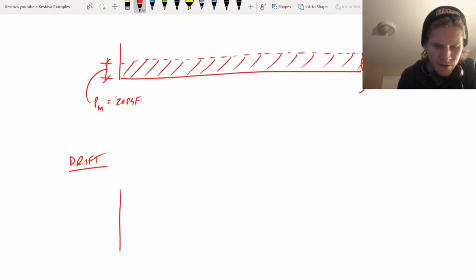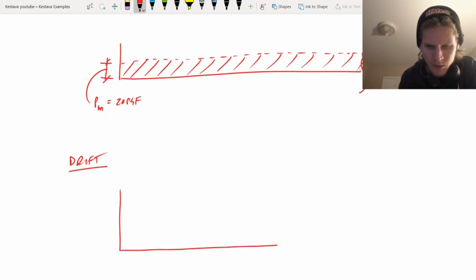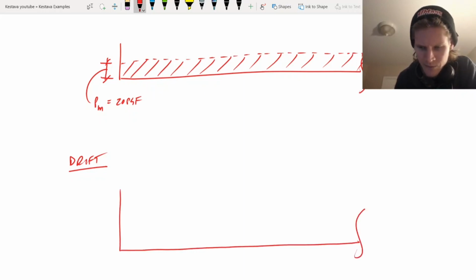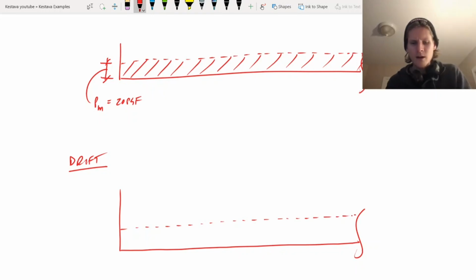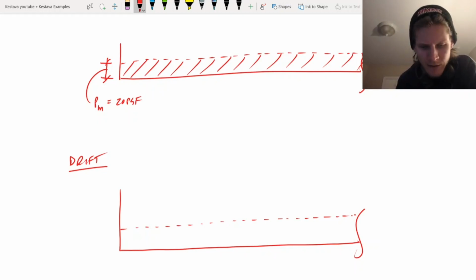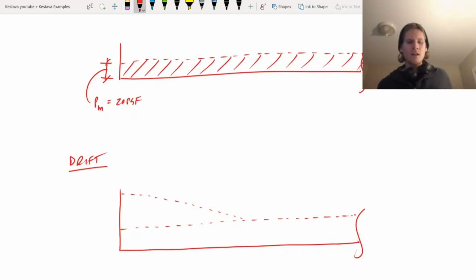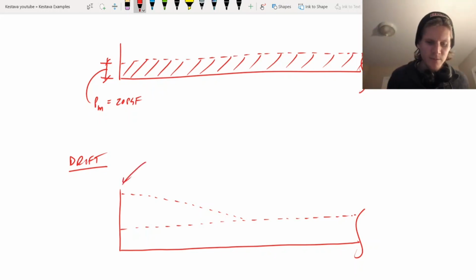Next, we have drift. I'm just going to draw it blown up a little more so it helps everybody out. First, we have our flat roof snow load, but it's not going to be the minimum this time because we also have the drift load along the parapet. So this right here is the parapet. I'm going to erase that just to leave us some space.